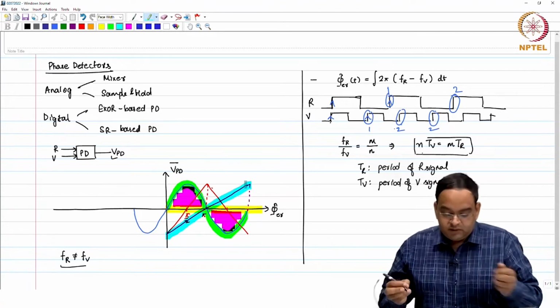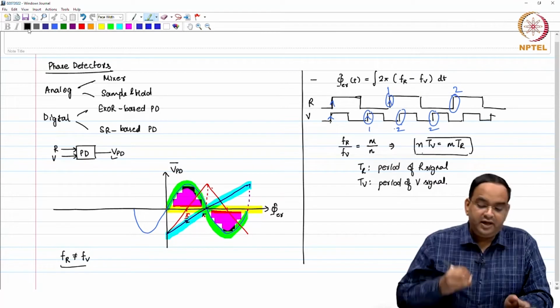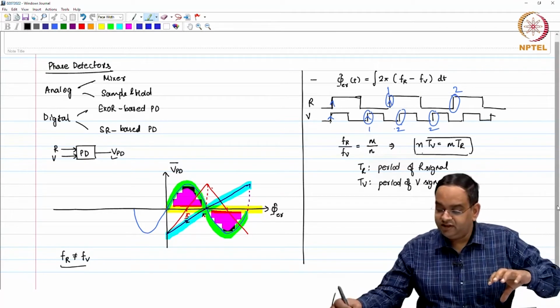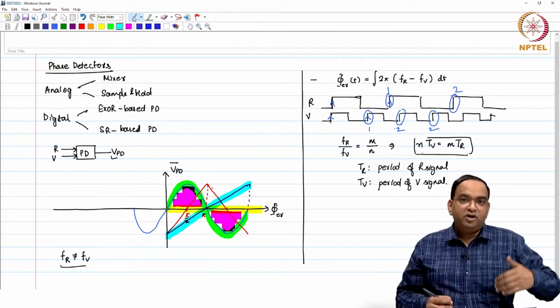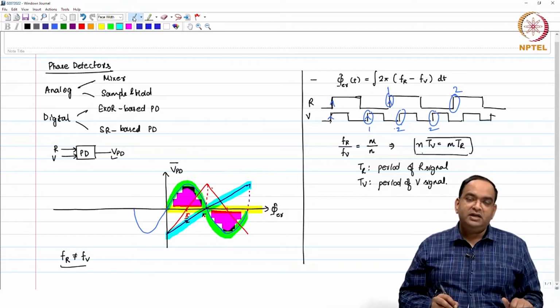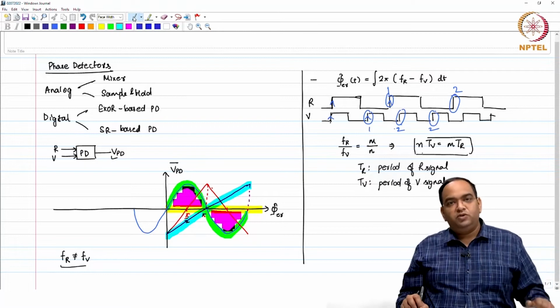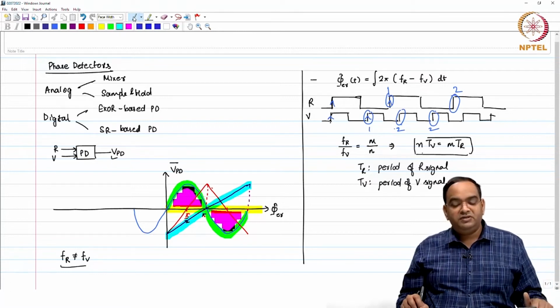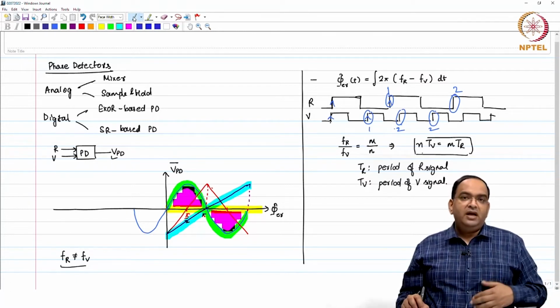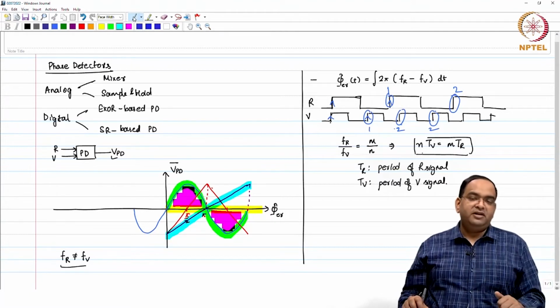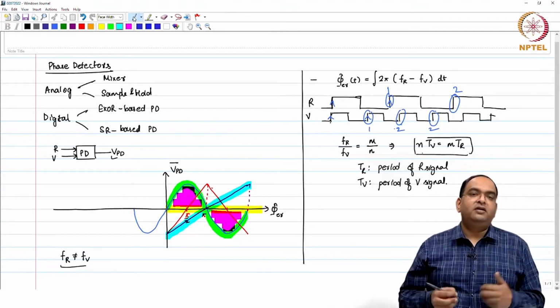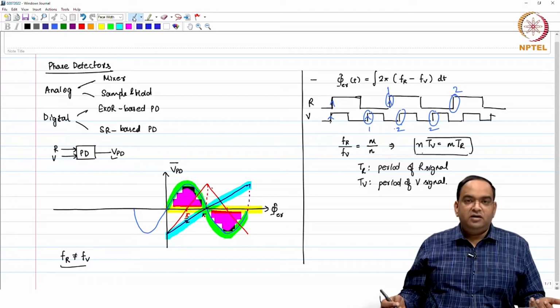Okay. So, the problem here is, first just understand this particular part: I have been using phase error detectors in the previous simple PLLs, where I used to also recover the frequency error, but here now I am saying the same phase error detector is not able to detect large frequency error.